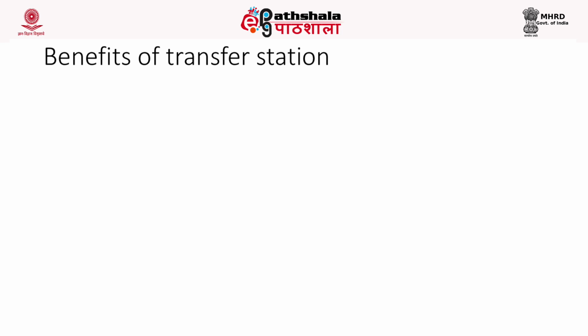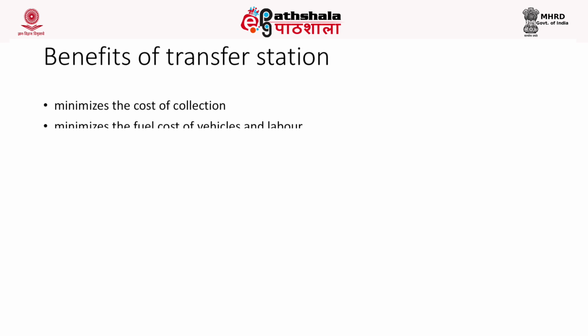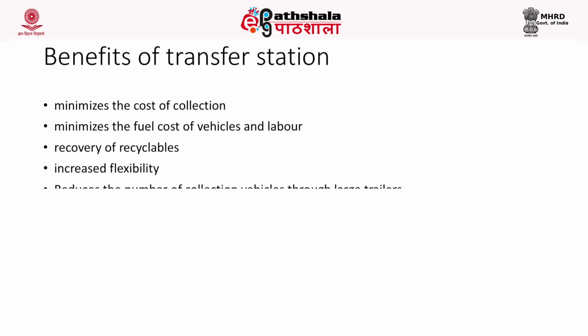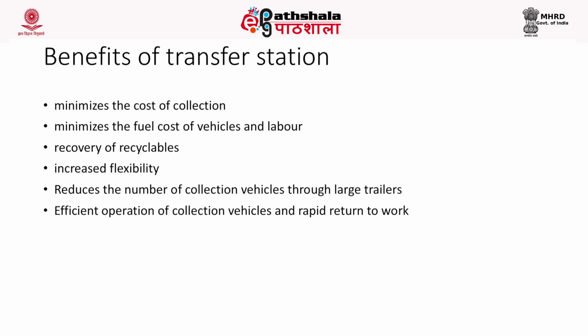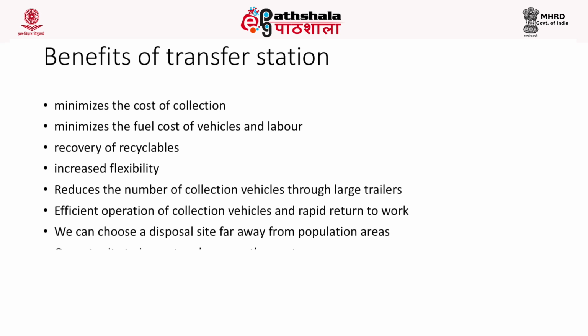Now let's look into the benefits of transfer station. The benefits of transfer station would be to minimize the cost of collection, minimize the fuel cost of vehicles and labor. Also, it helps in recovery of recyclables. It provides a lot of increased flexibility. It reduces the number of collection vehicles through large trailers, and also gives efficient operation of collection vehicles and rapid return to work. We can choose a disposal site far away from population areas when you have a transfer station installed in between the collection and the disposal site. Also, they provide an opportunity to inspect and process the waste.